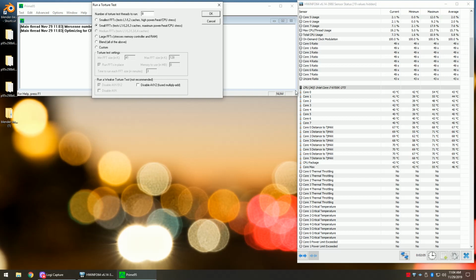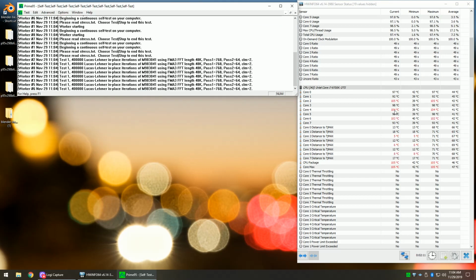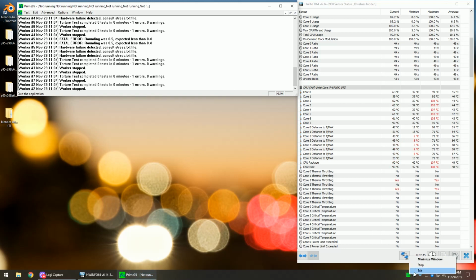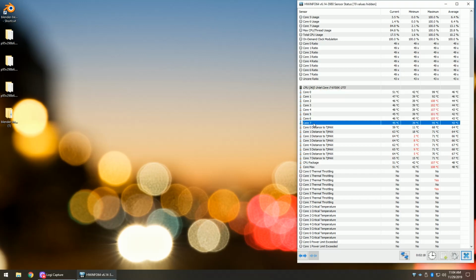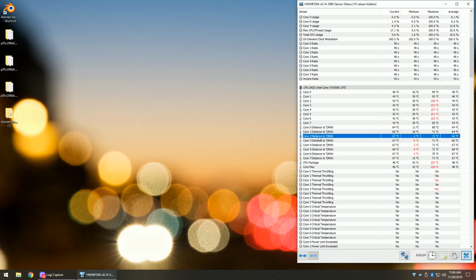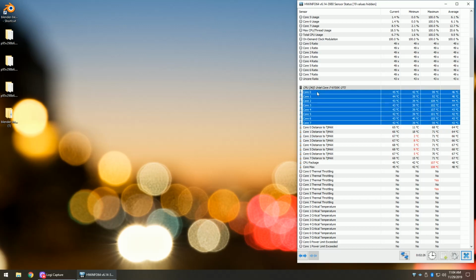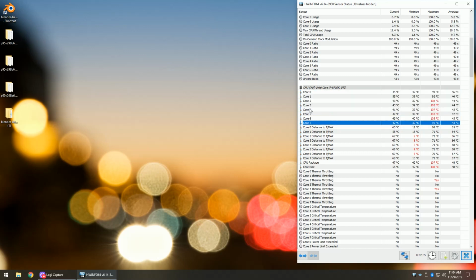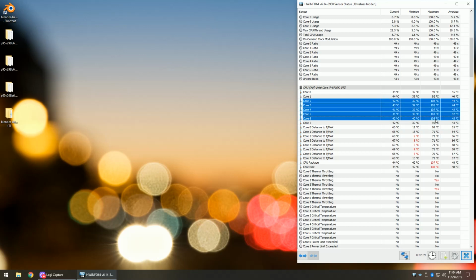And what we're going to see here is right now we're running at about 40 degrees Celsius. I hit OK. We're already in the 50s and now 90s and hundreds, you see here. And I can go ahead and just stop or exit Prime 95 at this point, as it's already hitting errors. This is a workload that I would never expect to run on my processor, and due to its power virus type workload that it's putting through the processor, it's generating a lot of excessive heat. And due to that excessive heat, you're starting to see 108 degrees Celsius, etc. here. And if it was able to run any longer without errors, it would likely be even higher in temperature.